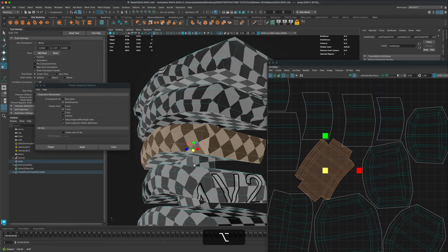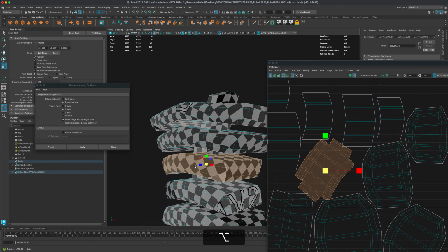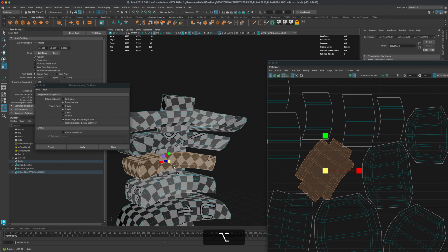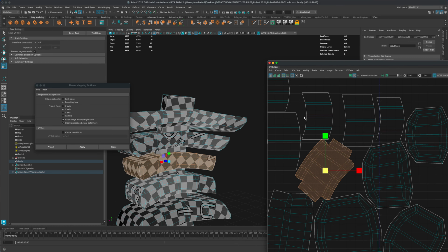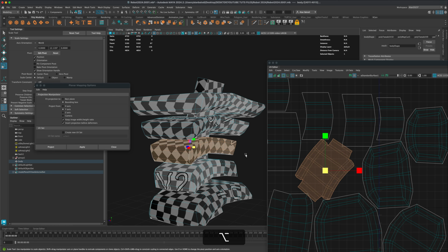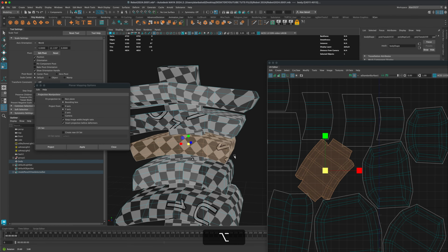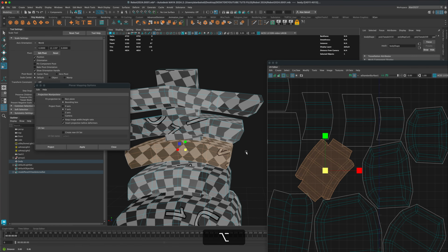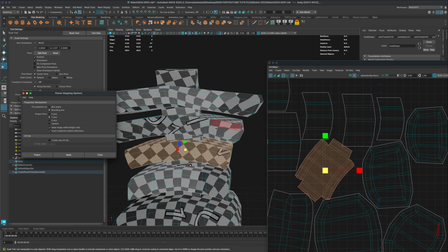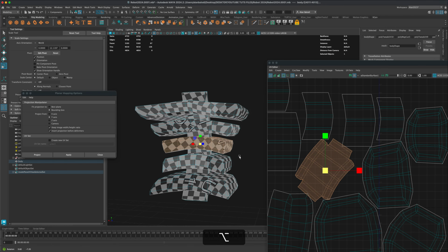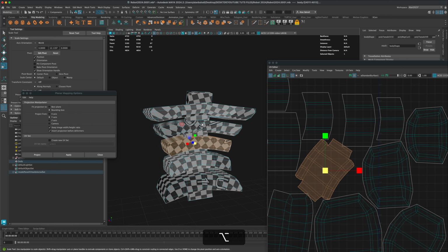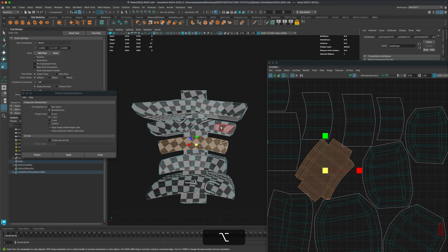So that's kind of a UV 101 that you need to understand when you're previewing it by clicking this button: how is the texture you're going to be painting in Substance Painter going to work on your mesh, right? So for example, if this had a pattern like a stripe pattern or something of that nature, it's going to get completely distorted in Substance Painter, which is terrible, right? But if this is a simple solid, you know, rubber or plastic, then this will work just fine.